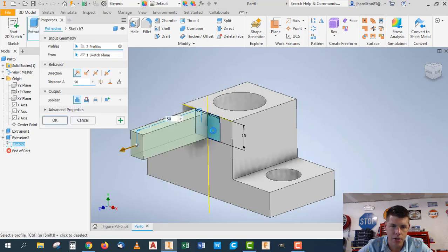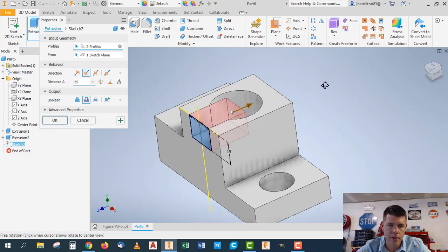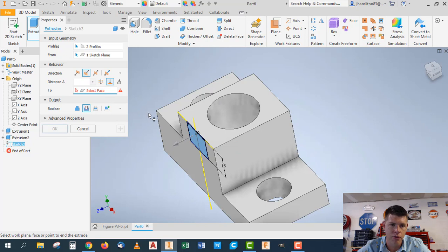We're going to extrude a cut now. So choose your two sections, switch to a cut operation, and how do we decide where to go to? So you could key in a distance, right? Just find a number that works, like 25, as long as it cuts in far enough. If you want to do this with a little bit better design intent, we can try the 2 option and see if we can cut to the inside face of this circle.